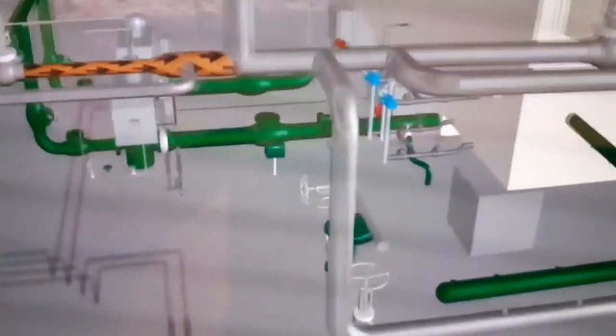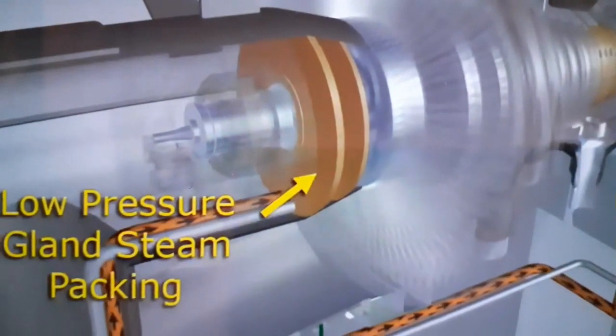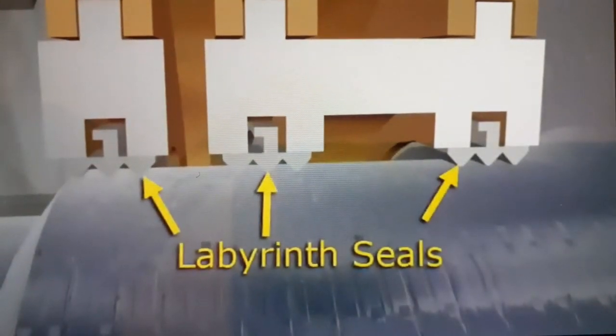condensate spray the gland sealing steam to the LP gland is de-superheated to an acceptable temperature, or the LP end of the turbine. The low-pressure packing is located on the condenser end of the turbine rotor near the number 1 journal bearing. Steam turbine shafts have been designed with a feature to prevent steam leakage called labyrinth seals.